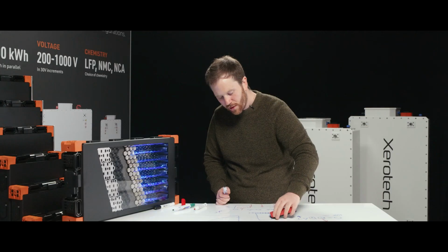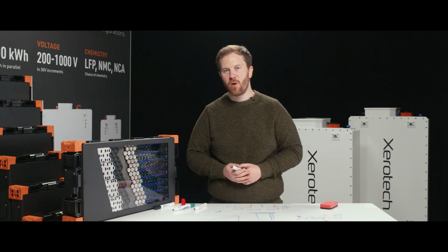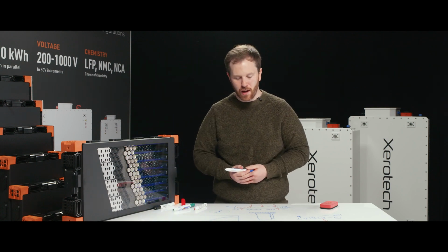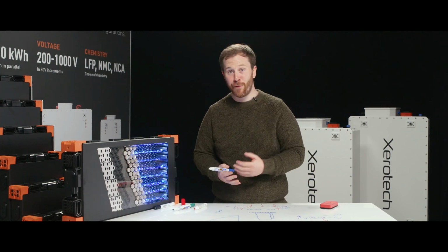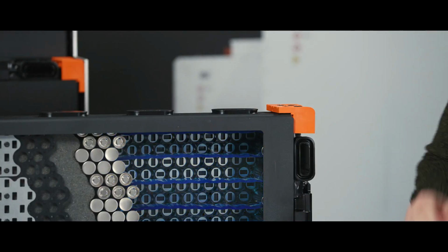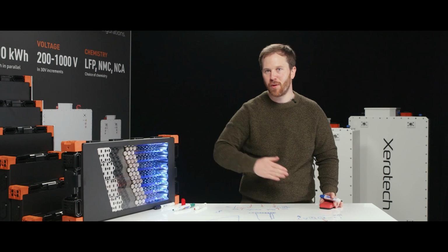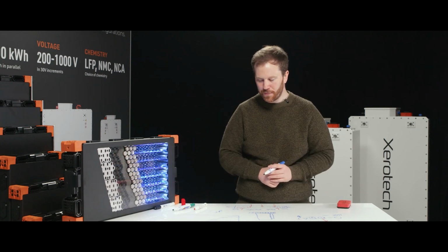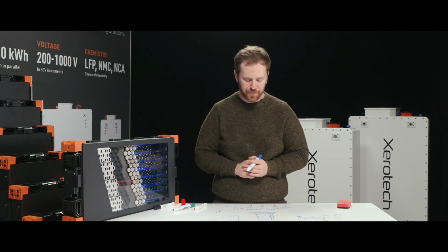So the pressure drops, and you'll see this in our data sheets and our catalogs, they're an order of magnitude lower than what everyone else in the market has. And where that's really exciting is it means that we can have an order of magnitude higher flow rate through our modules, through our packs than anybody else, which means our temperature gradients are much lower. Our heat transfer is much higher in that case. So this is really, really important for controlling the temperature of battery modules.